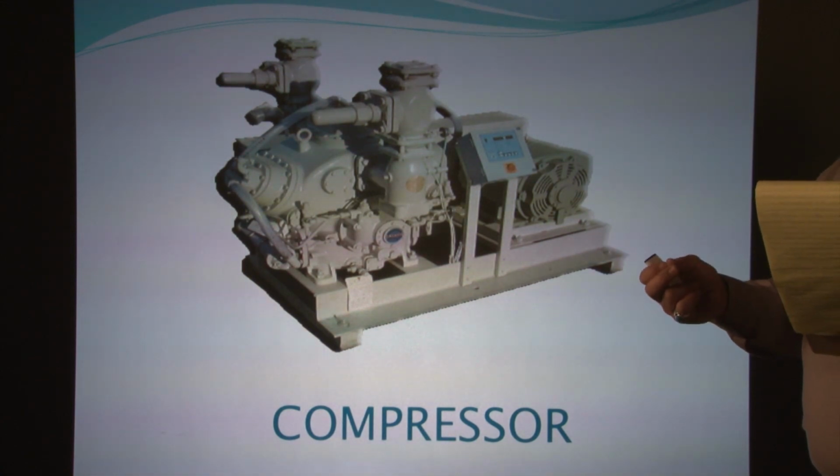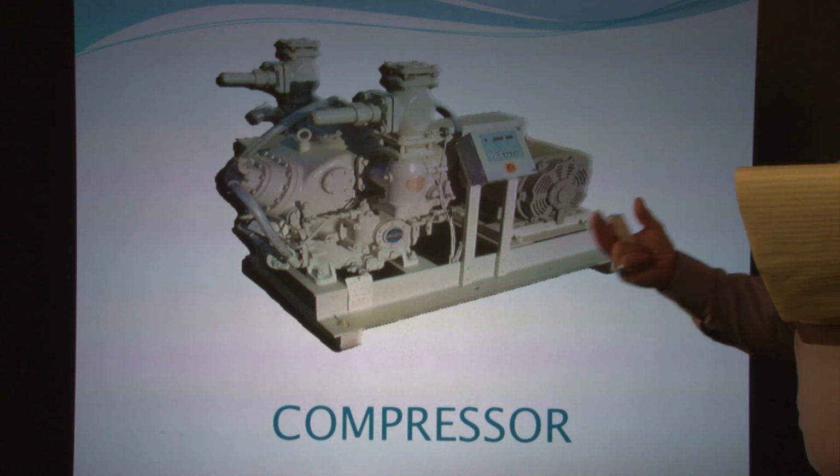Refrigeration and air conditioning compressors also remove vapor from the evaporator. The air conditioning compressors are large-scale mechanical devices and are designed specifically for air conditioning systems. There are three main categories of commercial air conditioning compressors, and they are the screw type, the scroll type, and the piston type. The screw type compressor